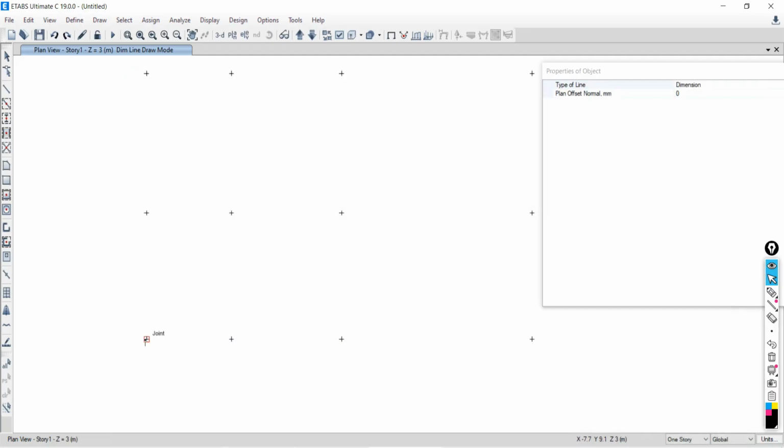If you click on this first point and take it to the point, it is 4.6. Now my intention is to turn off this command. See, the continuity is there. So I would like to turn this off. So right click on your mouse. Once you right click on the mouse, the continuity will be stopped, but the command is active.